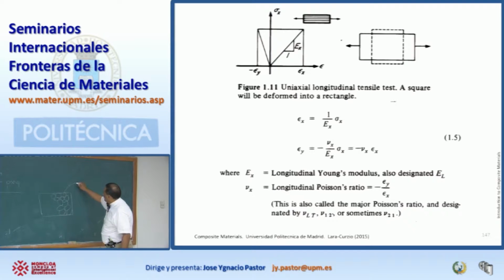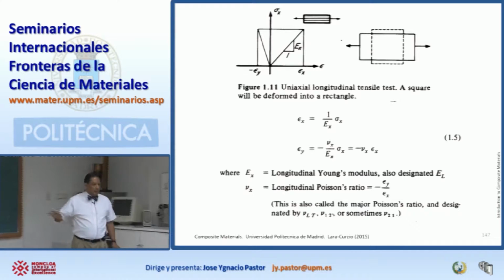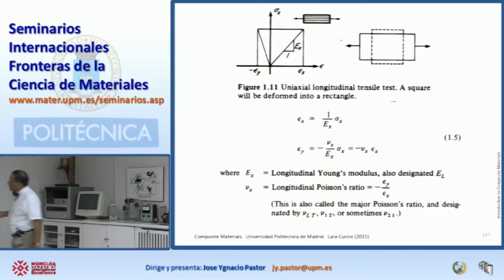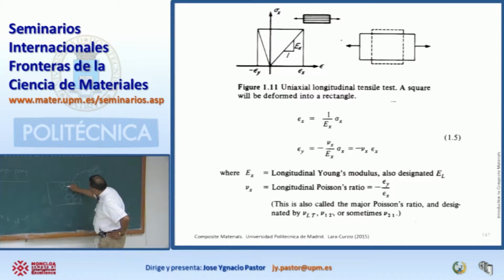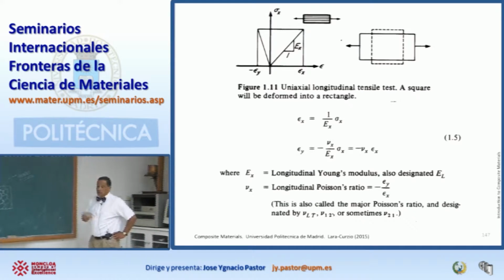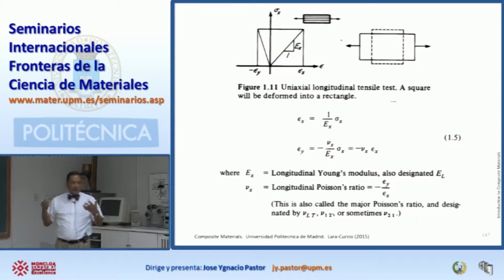you're going to see these are called grains. If you do this for a metal, you're going to see this. This is called the microstructure of the material. And you're going to see that these are what we call the grain boundaries. And it's going to look beautiful. This is called metallography. If you do a nice job, these microstructures are incredible.